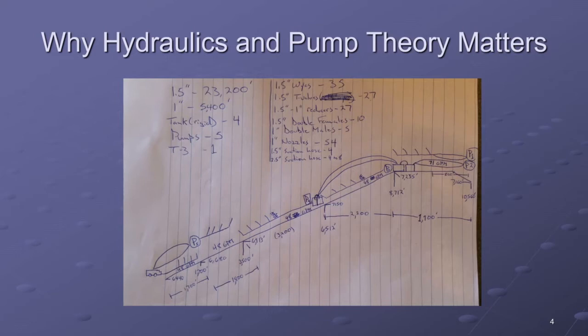In the example in the picture here, there's 232 sticks of 1.5-inch hose. And it's a real division on a real fire that someone was trying to pump water on. There's 5 pump stations, there's storage built in, there's supply for that storage, and nozzles being fed all at the same time. Okay, there's a lot going on here. It requires a clear plan, and you have to get 5 pump operators working together to facilitate the outcome. So, taking a minute to make a really good plan when you're dealing with this much complexity is a really good idea.